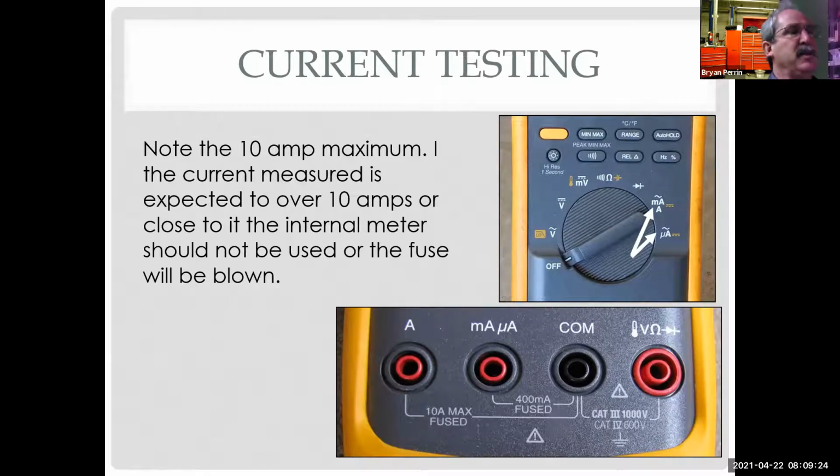The Fluke meter that we see here is a very good meter. It's a fairly expensive meter, and the fuses are very expensive. Other meters, like my Vantage, which is a graphene multimeter and has a lab scope built in, use a regular plastic automotive fuse that I get for 20 cents each. They're both 10 amp fuses. So needless to say, I like using my Vantage for testing more than my Fluke because the fuse is cheaper. It's more tolerant of my mistakes. And sure enough, that's what I blew the fuse in, my old Vantage. So those are the precautions for amperage.